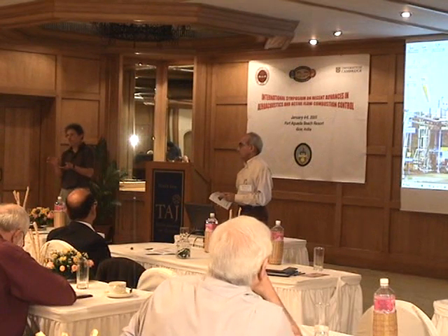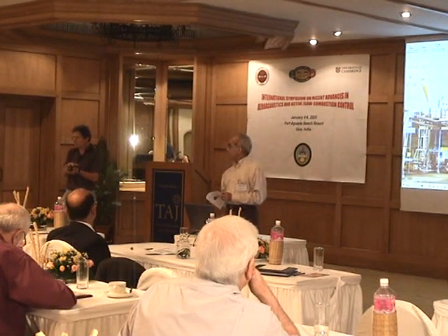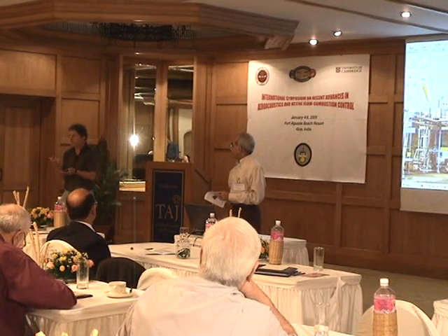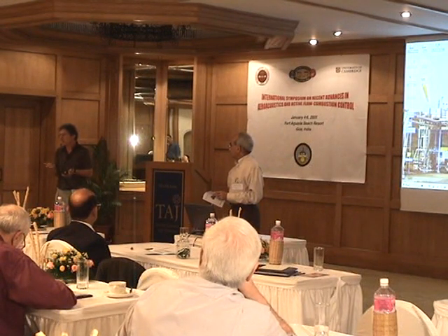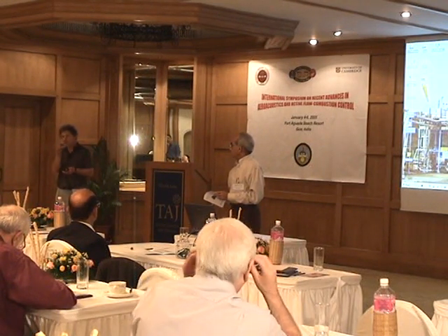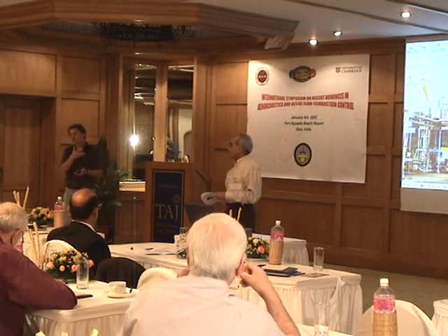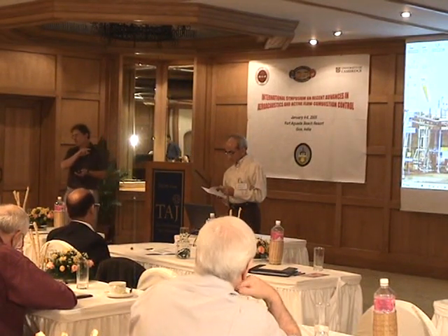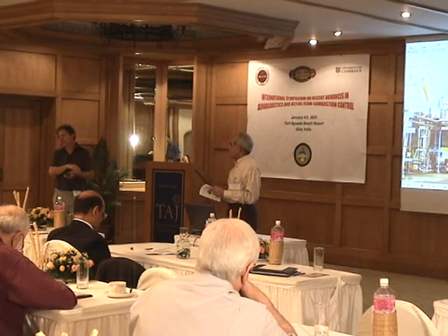So what has been implemented particularly in the US, but also by DLR, is individual blade control. That is, the actuation is in the rotating frame, and then you can actuate with any kind of frequency. And by doing this in flight, DLR obtained a very good result. So it was related to the four per rev and to the torsional response, because the first torsional mode was close to four per rev.